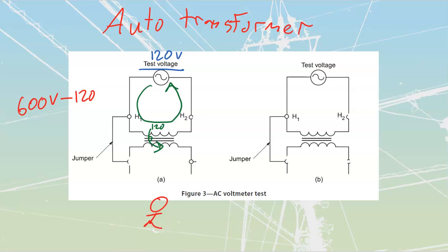I'm going to hide that one there again. If I have 24 volts, it's going to be down here. What I see is I've got 120 volts. I've got a jumper going across here where I'm picking up one side of that 24 volts. This side stays open. Then I'm going to take that 24 volts and pass over to here. Now what I'll do is apply my voltmeter onto it.